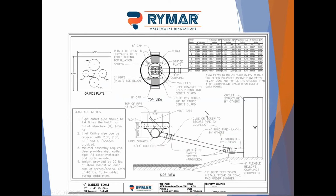So this is our typical detail. This is our new design. We're going to talk about it briefly here in just a second, but a couple of changes. We've shifted it now, so all the weight is on this bottom portion here, and we've got a float above. We also have a customized flexible bellows type coupling here. That will flex about 135 degrees, but it also stays relatively rigid to keep the skimmer in place out in the basin where you need it to be.